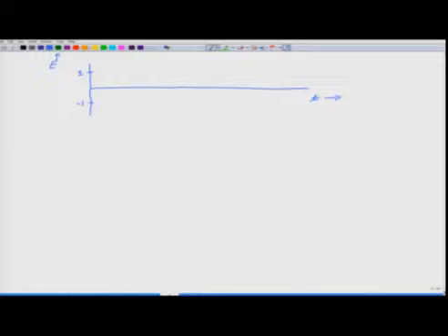So, I am considering plus 1 and minus 1 being the maximum and minimum of the amplitude of the carrier wave, and if mu is equal to 1 divided by 2, I have to consider half as the amplitude of the modulating wave. So, the modulating wave will have a maximum here and a minimum here. So, this will be basically 1.5 and this will be 0.5.